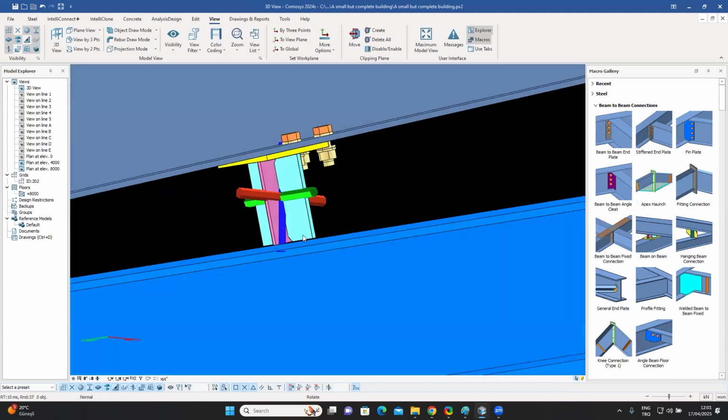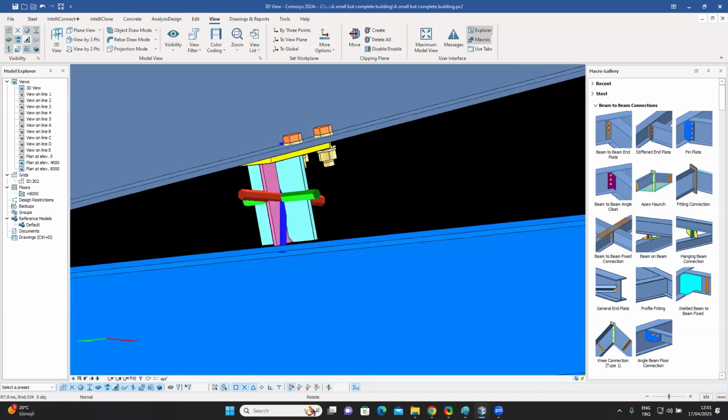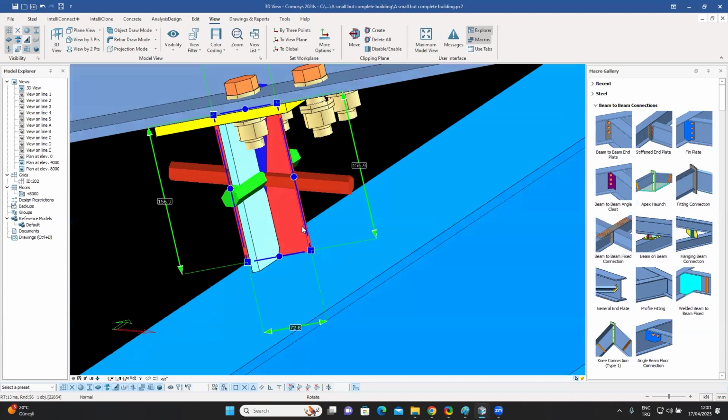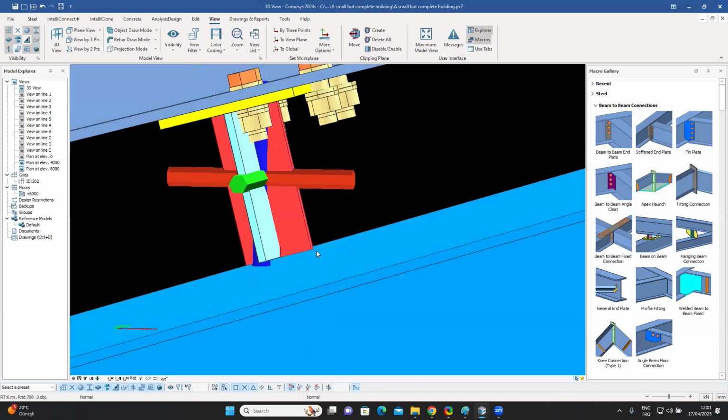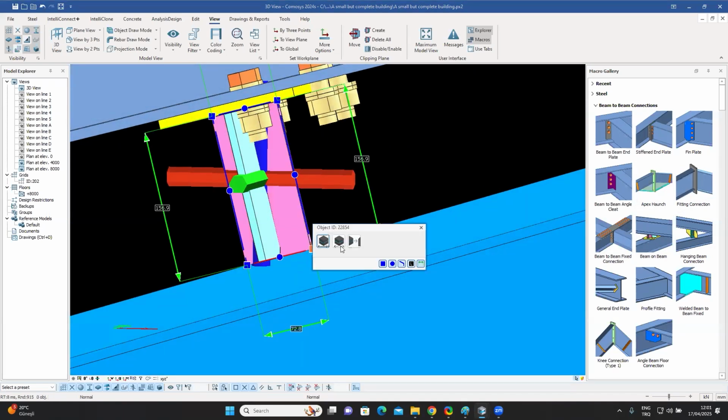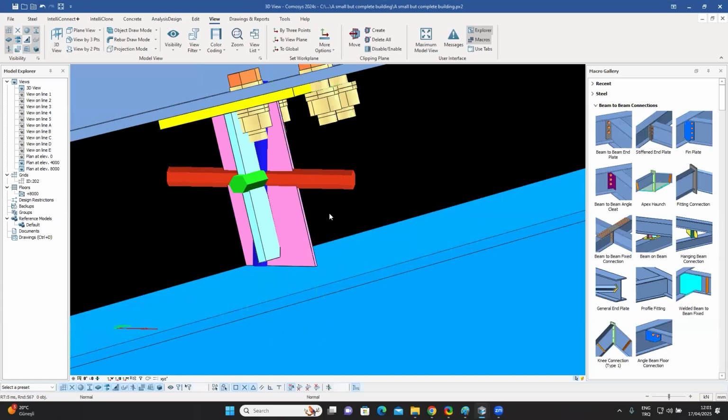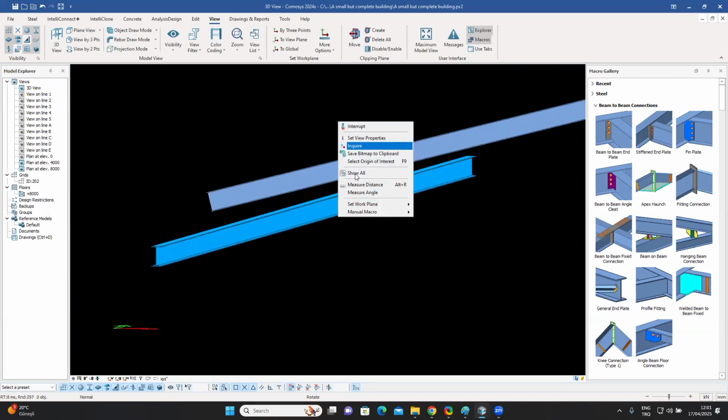Yeah, so I can see that this one is not extending. This pink one is not extending to the top. I can just select this edge over there and say just move to the surface. And when I do that, it's extended. So when a macro doesn't work perfectly, it doesn't mean that you're stuck with it. You can still use it as much as you can, and then continue from there manually. Now, let me turn everything on again.